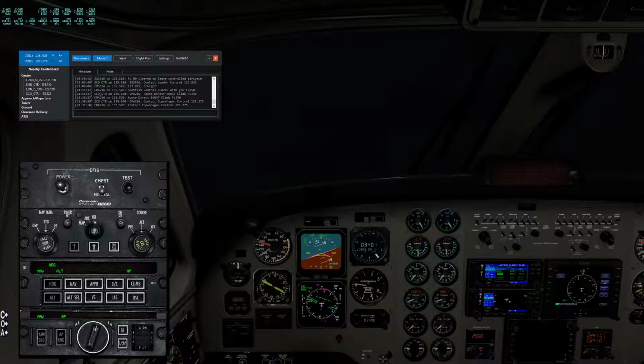And now I'm going to move the course by 10 degrees at a time, swinging it round to the west. So I'm a little bit overturned here, so I hold the heading and turn the bearing pointer another 10 degrees. I think that's the 30 degree radial now. And you can see now we've got sort of a 90 degree angle between our heading and the radial, which means we're on the arc.